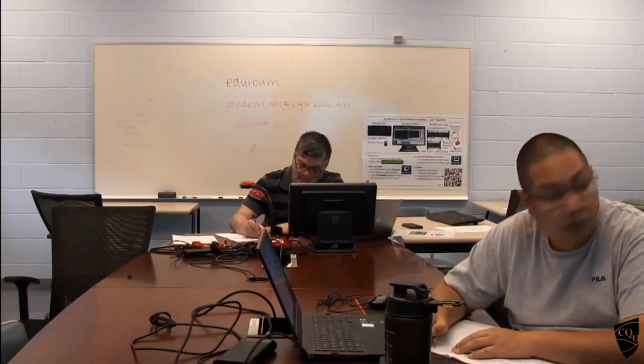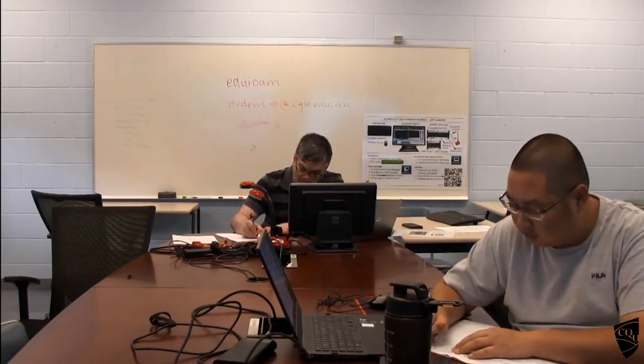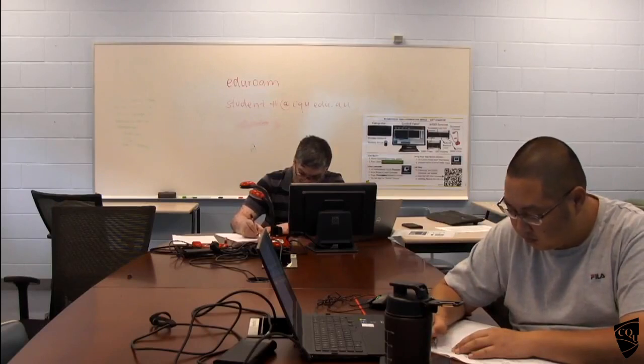It is 5 upon 384 W L to the power 4 over E I. E is the elastic modulus. The I value is important. Stiffness.